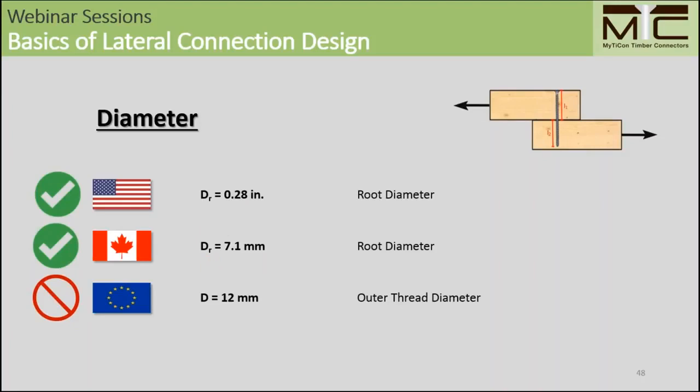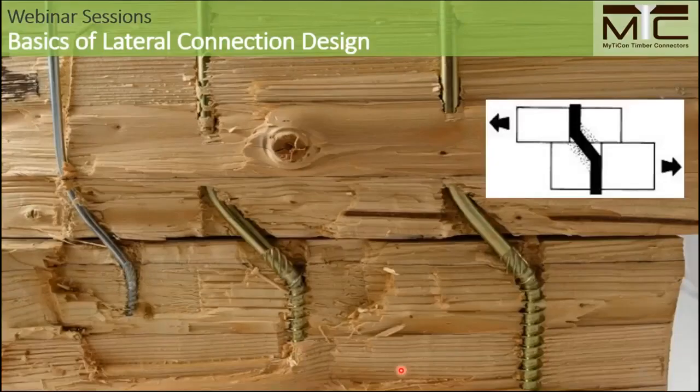I'm just going to pull up that picture from earlier. It can be seen here. Yeah, this is the formation of failure mode 4, and you can see that there are actually different diameters within this failure. So here you can see this is the minor diameter, so this is the smallest diameter that we find in the screw, or also we say minor thread diameter. And here we can see that the yielding of the fastener actually happens in this portion of the screw, but we also have yielding in the shank diameter here. So this is an interpretation.